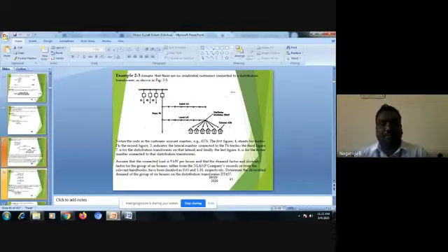Demand factor as well as diversity factor are given for the six groups. So determine the diversified demand of the group of six on the distribution transformer.